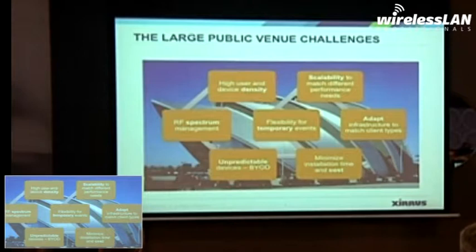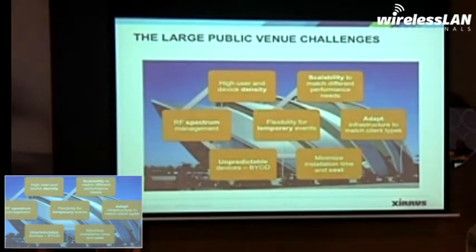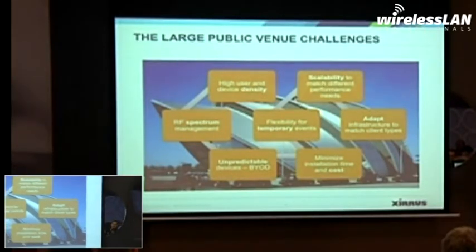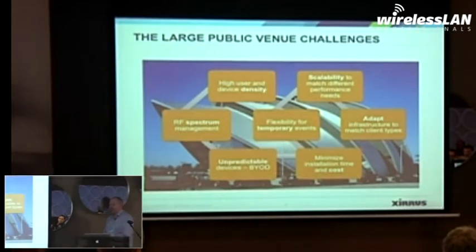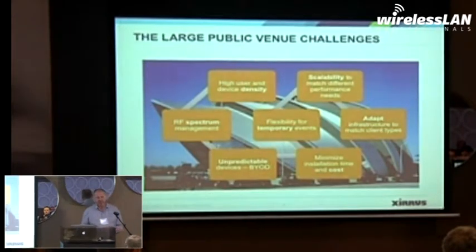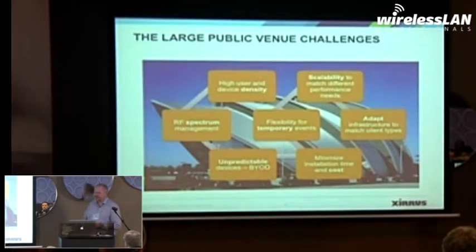Spectrum management. Very important. If you have a lot of devices, a lot of radios, it's easy to fill up the spectrum. In a design, you also need to build in some flexibility for temporary events. In most convention centers, you have a fixed installation, but for some events, they also require some extra radios in some locations, so you need to design for that as well.